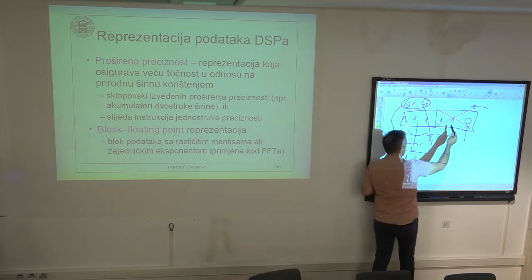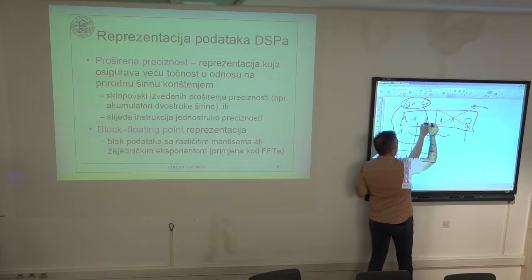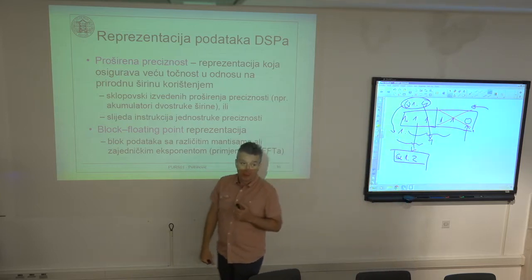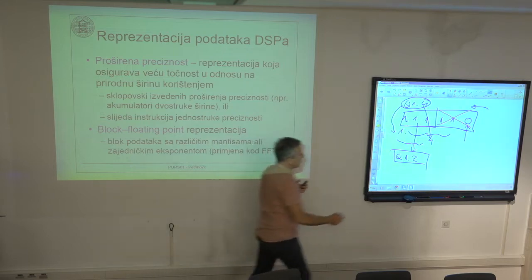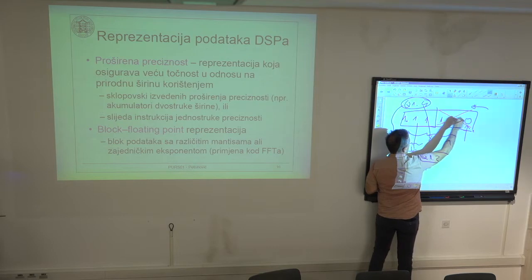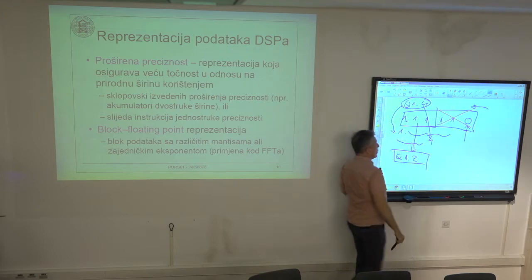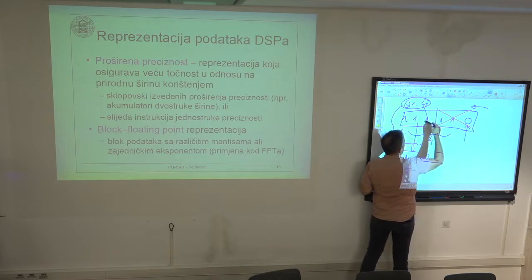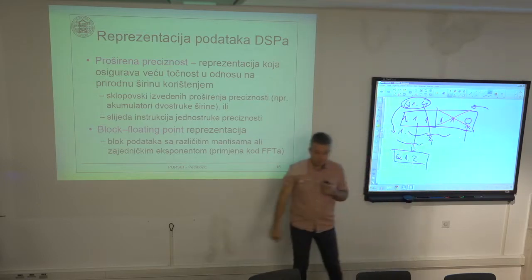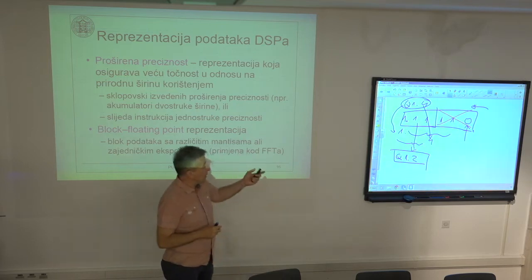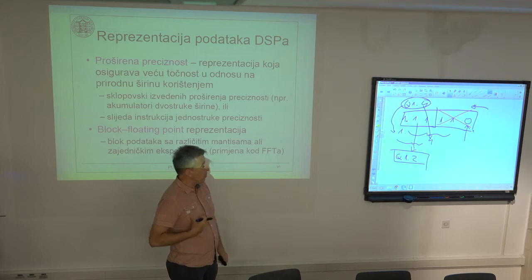How much less? It is at most one least significant bit of the upper word. Because if I have this 111 here as a lower word, and I reject this word, I simply throw it away. This 111 is almost the same as 1 on this position. So this 111 is almost the same weight as the last binary position of the upper word.